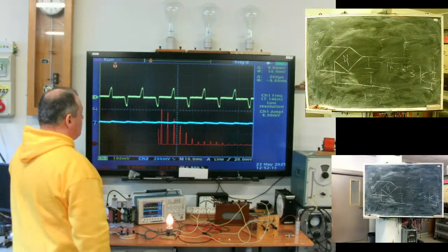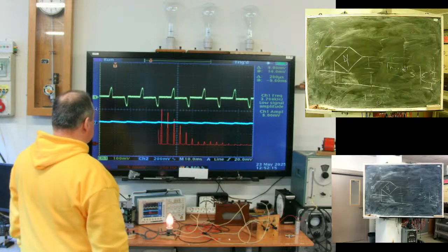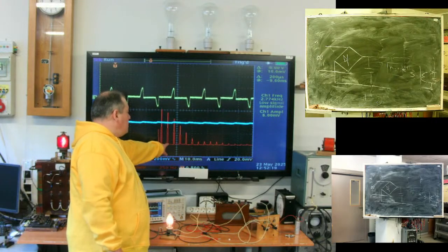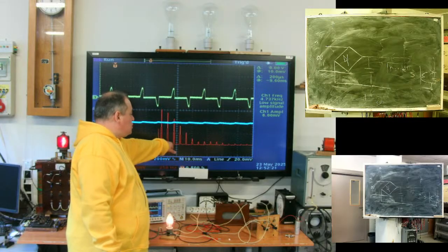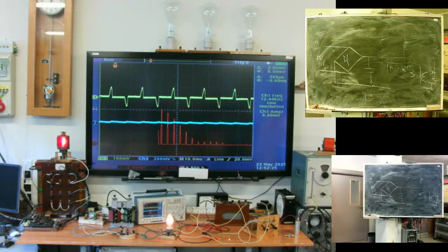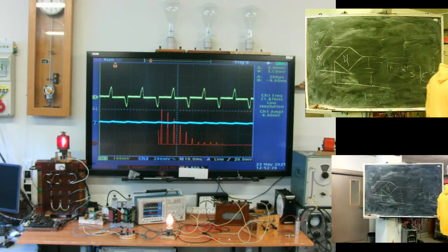But without it, in our nowadays reality, what we will get is current like this. This kind of current: base harmonic, rich in third and rich in fifth harmonic. It's the current of modern single phase loads.